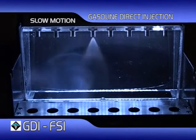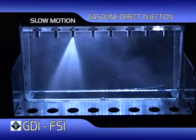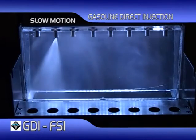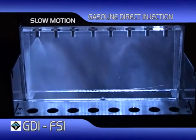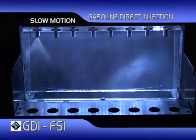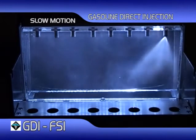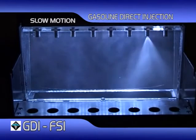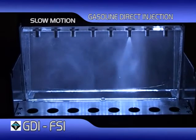If you look closely, you will see different types of spray angles and spray patterns. A visual check of the atomization is also possible to the trained eye. The various vehicle manufacturers all have their own injector designs and have injectors produced to their own requirements. The most critical factor in the GDI injection system is the fuel distribution and atomization. A shortage of fuel delivery can be easily corrected by the lambda control system, but any intermittent changes in fuel distribution or atomization are corrected by the short-term fuel trim as part of the adapted engine management system.